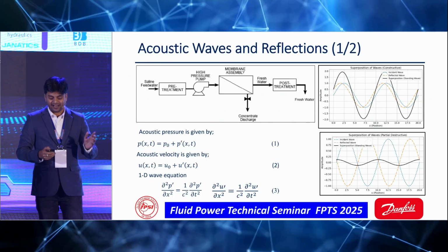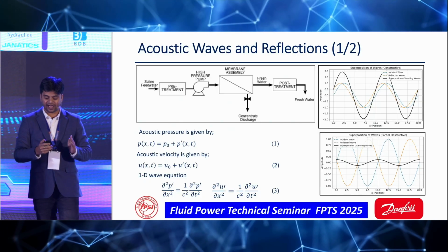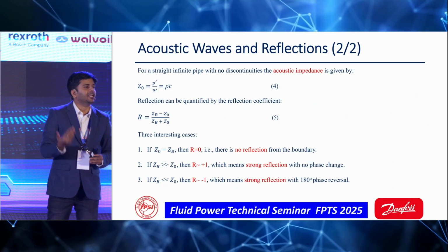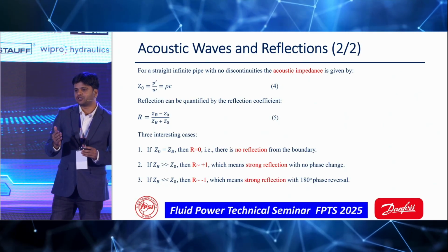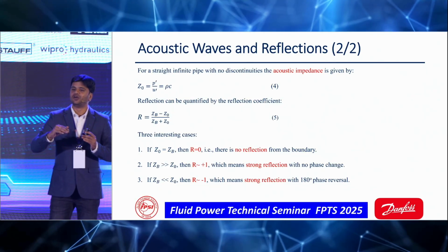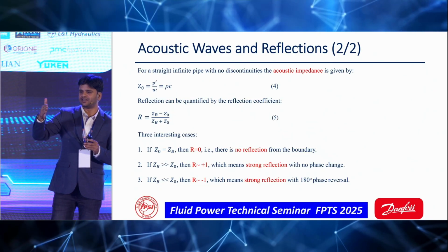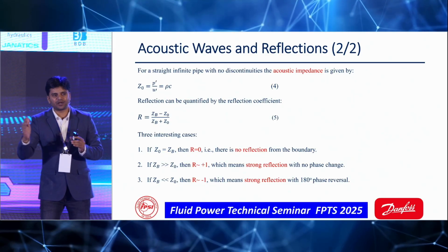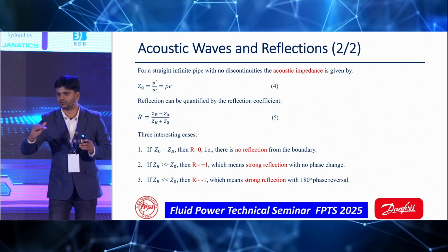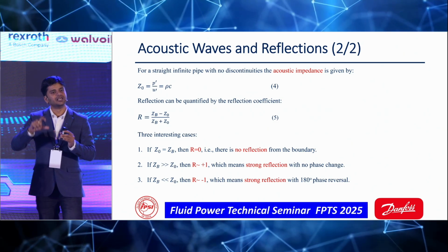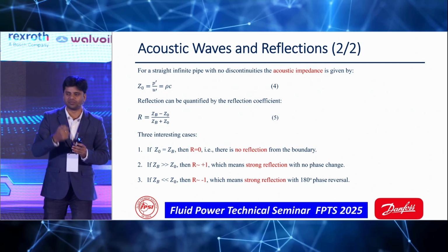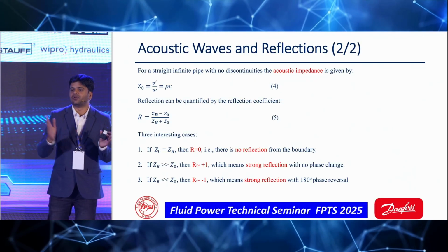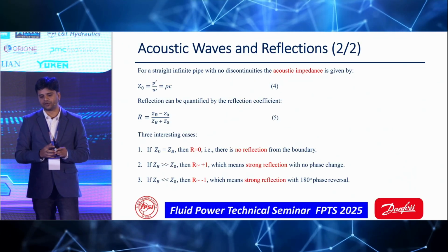So acoustic specialists can help us understand how these pressure waves affect us. There is a term called acoustic impedance, which basically helps us understand, at each interface at the end of the discharge pipe, how these pressure waves reflect. When they reflect back, standing waves form in the pipe. When we have standing waves, if they match the frequency of the structure and the fluid, then there will be resonance. So we have to be extremely careful in how we model all these pressure waves.